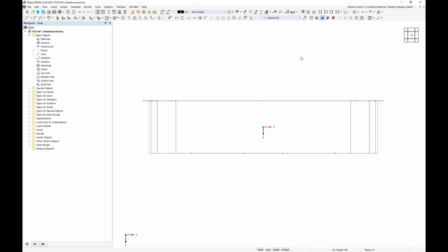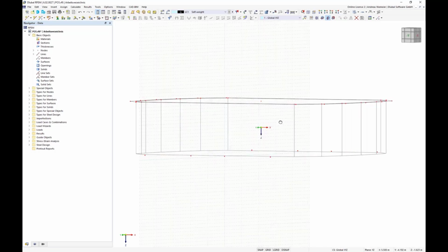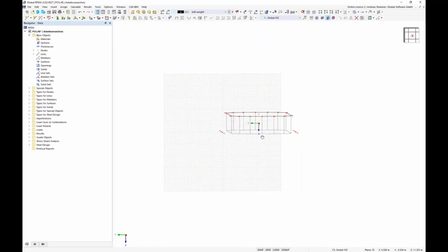And how to get this? For this, I recommend to use our working plane, so this dotted plane, and we will move the center of this plane, for example, to one foundation point. Now we rotate this plane into this intersection or in the plane of the arc, and will be able to create intersections here. For this, I use a surface.